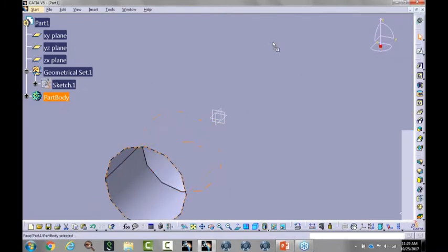And you'll notice, and I'm sure you've noticed this if you don't know how to change these settings, that should be a circle last time I checked. That has a radius value, okay? That kind of passed by us here. But it's actually a pentagon. Well, those are called chord lengths. And if you keep a chord length too long, then you get this ragged edged effect.